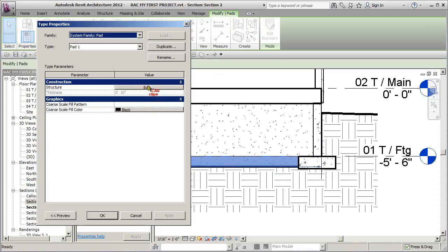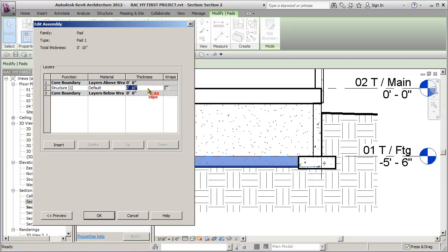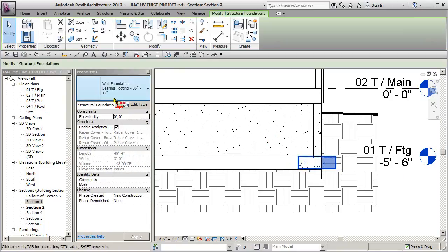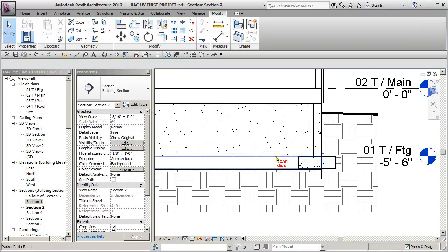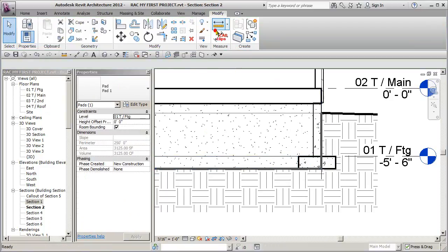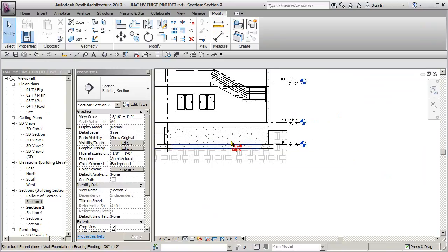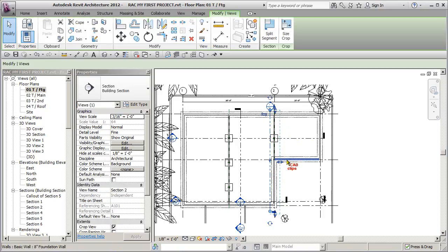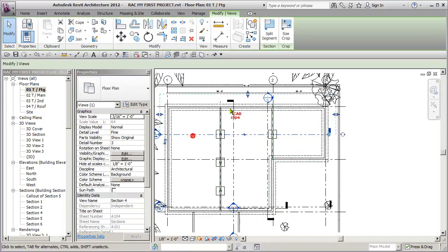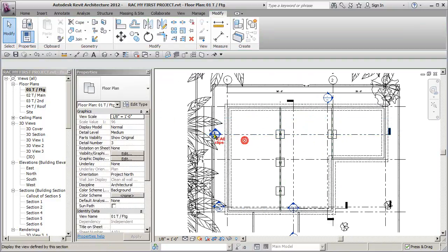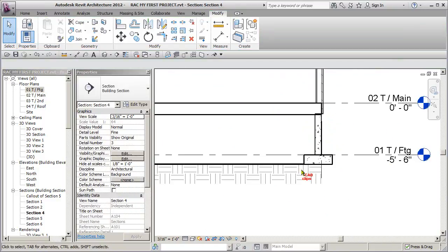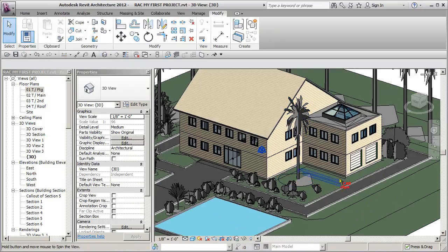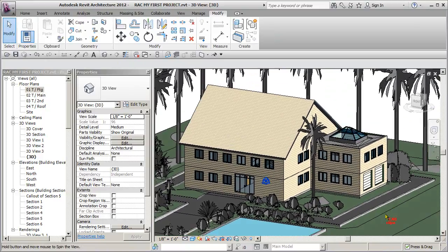Now my pad, did I change that thickness? Is it supposed to be 1 foot or something? Must be. This is a 36 by 12. Yes, so this has to be a foot thick, and then I turn it off, hide the element. Then you never see it. That line again is the footing beyond. If I go back to my top of footing, what I'm seeing there is the line beyond. Similarly here, if I pull this back, then I won't see that line beyond. So that's our footing pad in place. It's going to remove and excavate that material from the underside of our building.